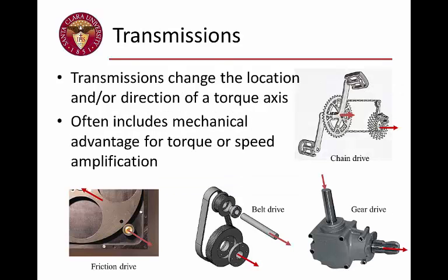We have things called transmissions. The point of a transmission is to change the location or direction of a torque axis. In doing so, it's very typical to also incorporate mechanical advantage into the design of the transmission, although that's not necessary. And remember that mechanical advantage allows us to amplify the torque or the speed, one or the other, in order to be exploited for the purposes within our device. And recall that if you do amplify one, you are going to cut the other.